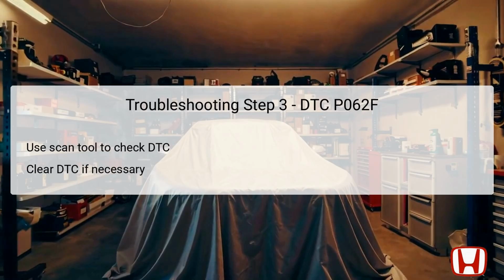Next, utilize a diagnostic scan tool to check for additional diagnostic trouble codes, DTCs. This is important because there might be other error codes present, either confirming an underlying issue or potentially conflicting with P062F. If any codes are found, they must be addressed as they may be related.